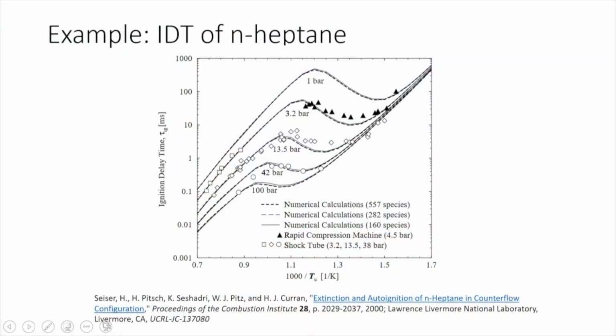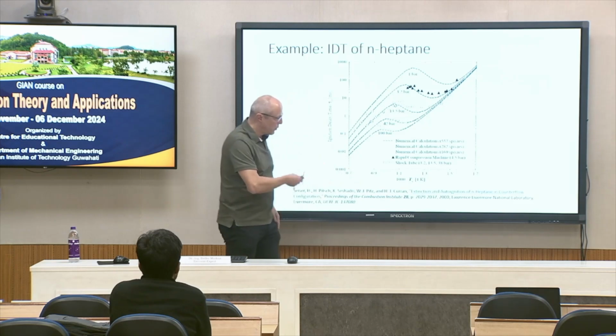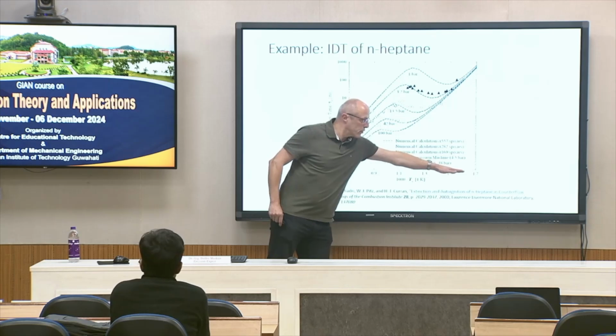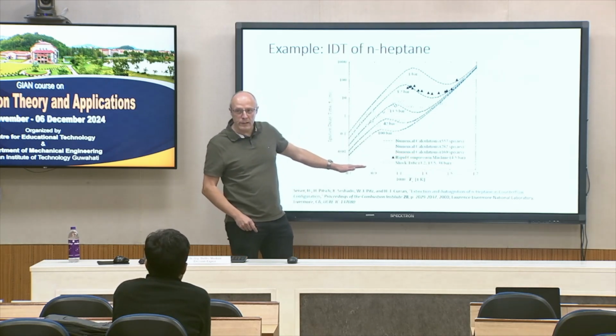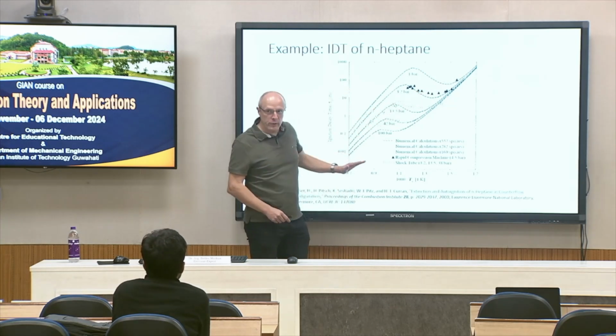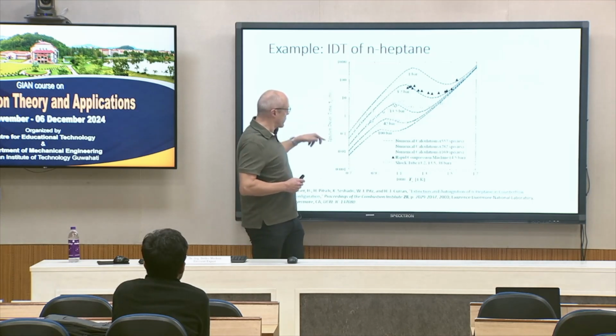So, here's one example from a tutorial of Cantera. We have here ignition delay time as a function of 1 over T, or 1000 over T. So temperature increases from here to here, and we have seen it yesterday. We would expect a linear decrease if we consider an Arrhenius equation, because we have a logarithmic scale here.